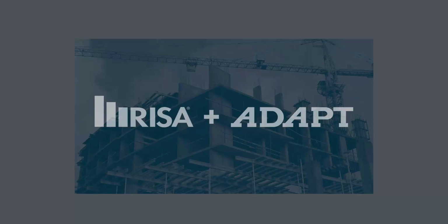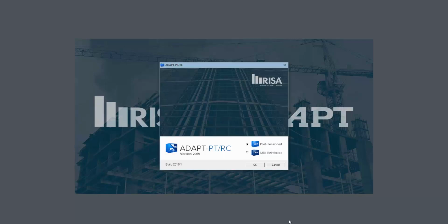In this video, we're going to talk about pour strips in ADAPT-PTRC. ADAPT-PTRC is a 2D program using the equivalent frame method for two-way slabs, and we're going to show how we can model two different tendons, allow for a pour strip, and allow for the program to calculate reinforcement through the pour strip. So let's go ahead and get started.